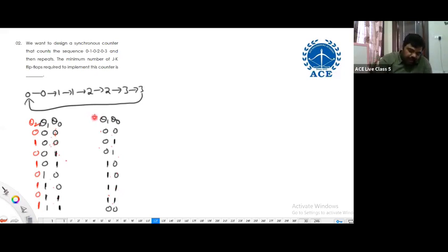Then what about the next state? Again, you need to write it because it must be matching, right? 1, 0, 1, 0, 1, 0, 1, 0. By designing the system, we read only Q1, Q0. For designing, one flip-flop is extra, but reading is only on Q1, Q0, two flip-flops. So one flip-flop is extra. The reason is there is an ambiguity in the state definition. That is the reason the ambiguity should be eliminated. How can I eliminate it? These two are not the same, which you understand, but to make the system understand, we add an extra bit. As it is only two possibilities, one bit was sufficient.